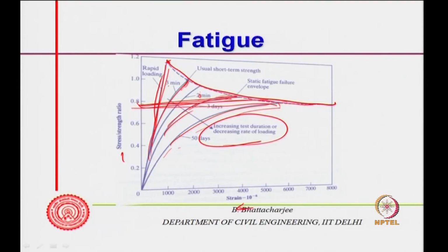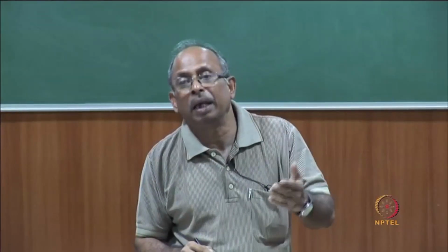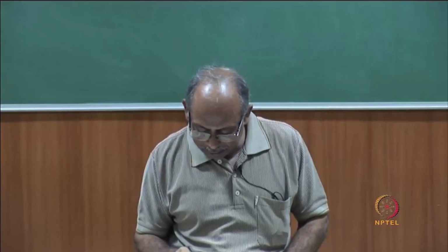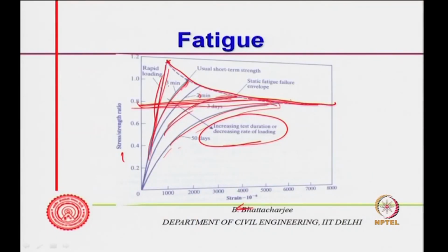You can call it the static fatigue failure envelope, because this is related to micro cracking or creep behavior and so on. If you load it quickly, it fails at a higher load. You take it for a longer period of time, it will actually fail after a certain period of time, because it is sustained for 50 days. So, it will actually fail.